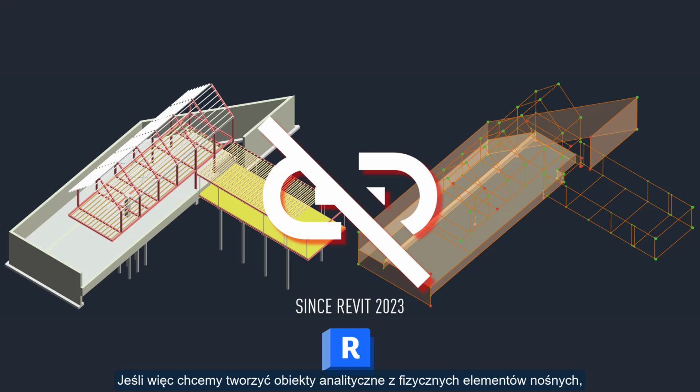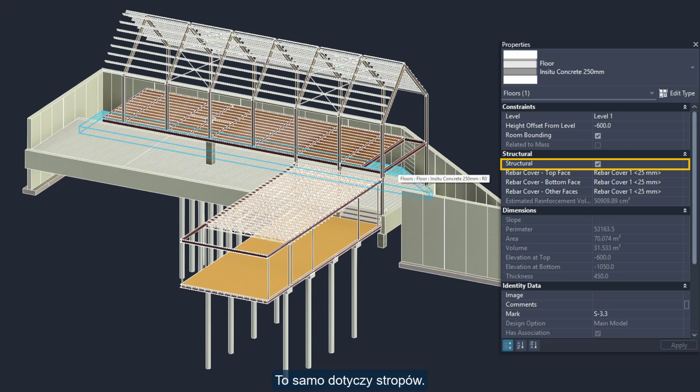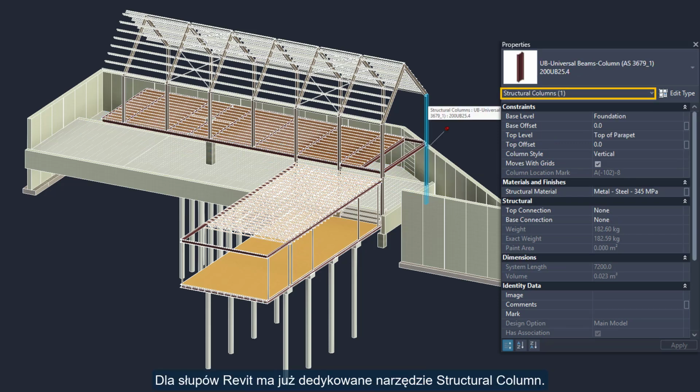So, if you want to create analytical objects from physical load-bearing elements, we first have to prepare the Revit model properly. For walls, the structural parameter has to be activated. The same applies to floors. For columns, Revit already has a dedicated structural column tool, so you don't need to set anything else.